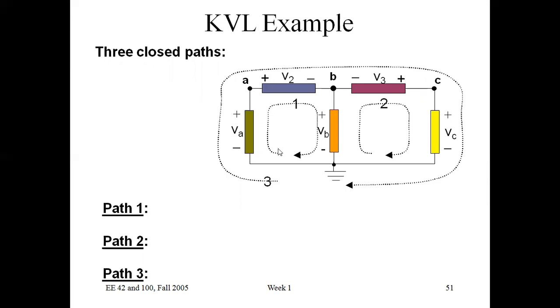Okay, so for this we can formulate the equations. If we move in this direction, here from positive to negative. So what is the sign convention for positive to negative? We are moving from positive to negative, which means there is a fall in voltage. Again here, positive to negative means fall in voltage, so it should be taken as negative.